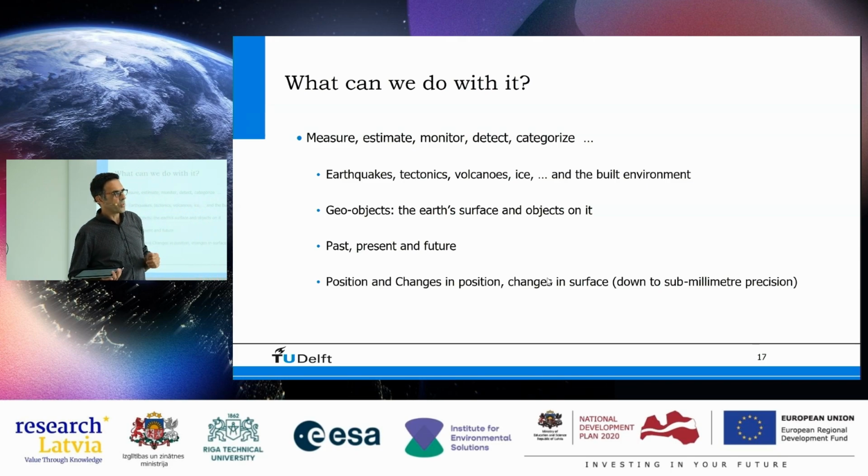So for example, in the Netherlands, the situation is such that we still have, of course, millions of kilometers of gas lines, but there are still 700 kilometers of brittle cast iron gas pipes in the Netherlands, and they are able to replace about 25 kilometers per year. I don't know the situation here, but that is a big problem. And we have had explosions because of differential motion of the street relative to the house, which made these cast iron pipes break, the gas came out, and there was an explosion. So what we're doing now is we're checking all those locations, all those 700 kilometers where we have the brittle cast iron gas pipes, and checking for differential motion between the building and the street next to it, right? So this is the type of intelligence that you can get from it.